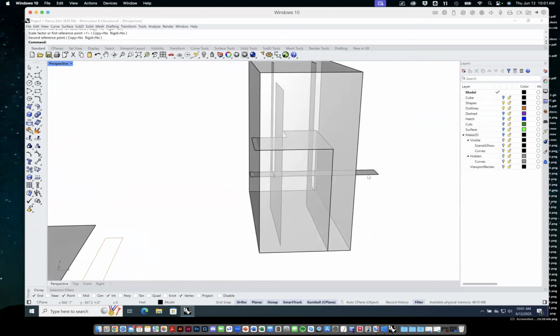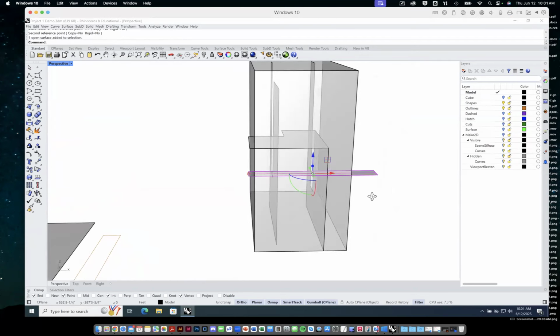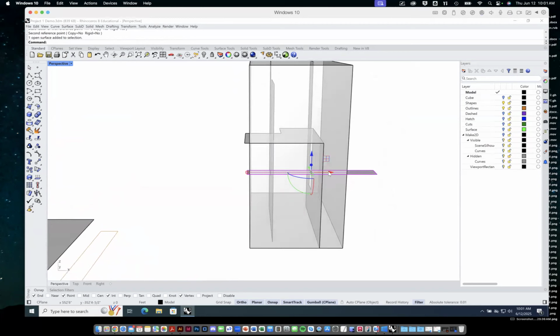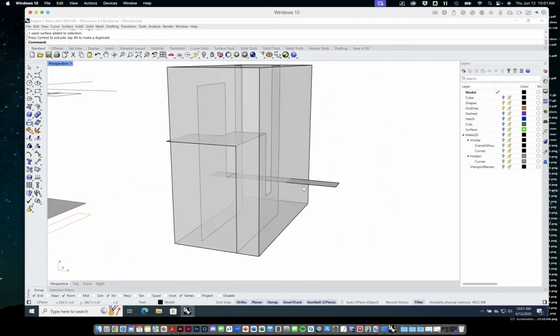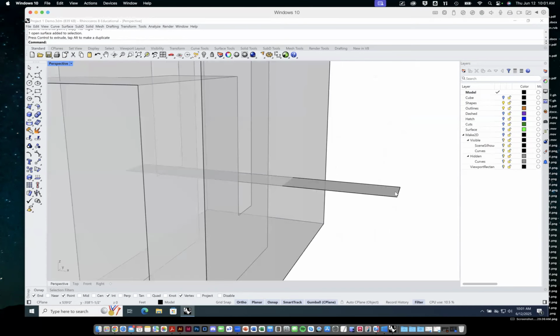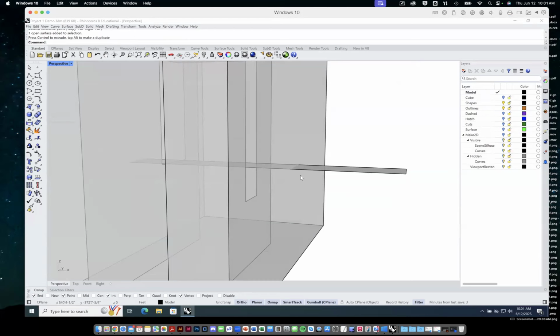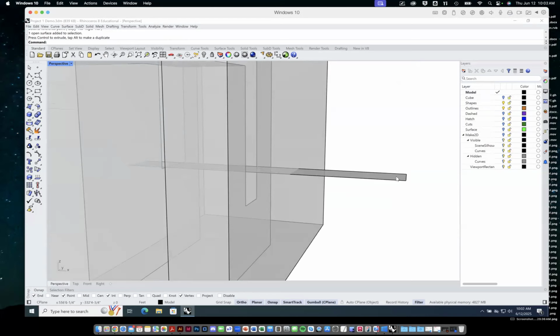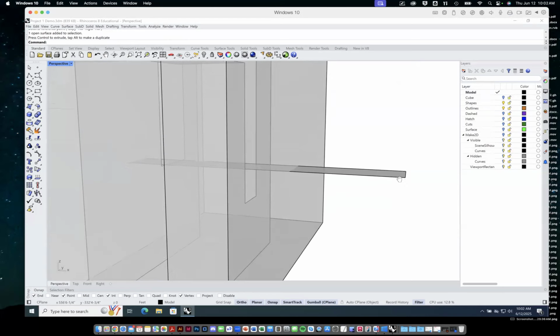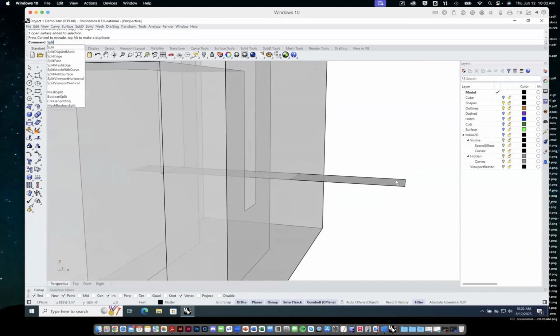So I have this component. You see it highlighted magenta, and it's sticking out of the box in two directions. I'm just going to slide this over using the gumball so it's not infringing on that volume. One of the things I can do here is I could always just trim it away, or I could split it and then maybe turn it upwards or downwards. In fact, it looks like if I split it and then turn it downwards, it could become a structural support that goes down close to the ground. And if it doesn't meet the ground, then I could stretch it with that scale 1D so it does meet the ground. So that's what I'm going to do. I'm going to say split, S-P-L-I-T. Again, I'm just typing this into the command line.